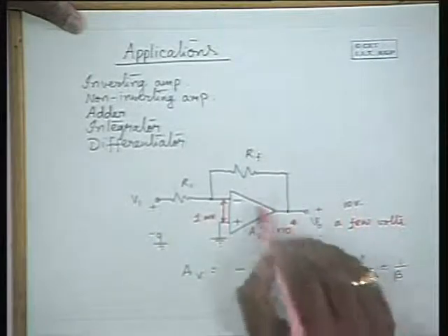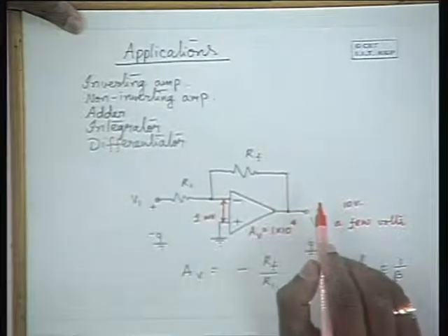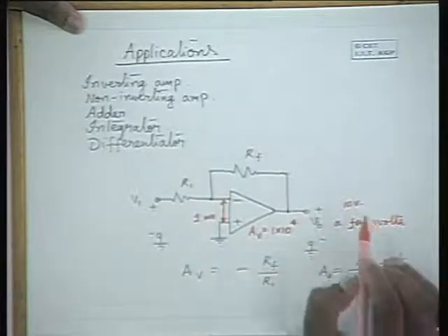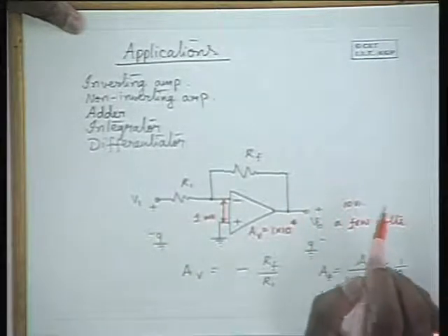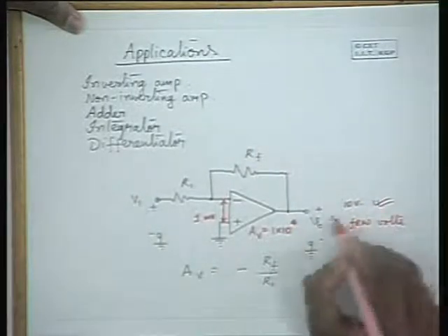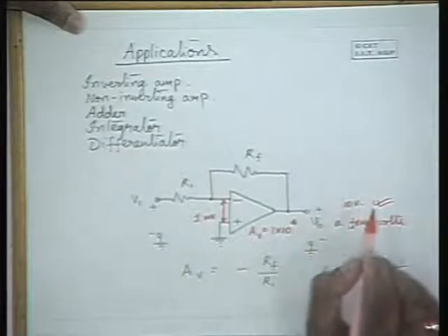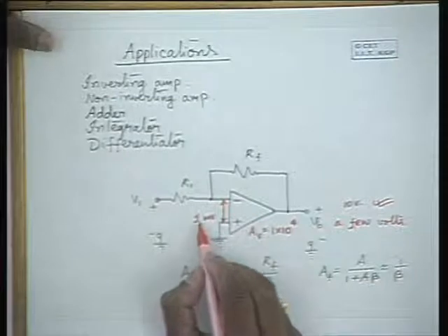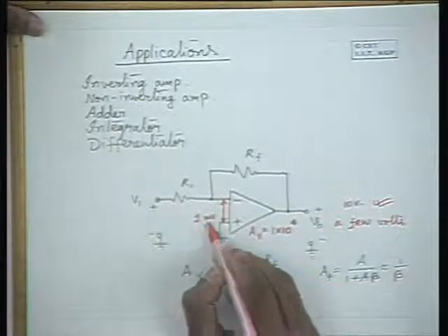And if the amplifier doesn't permit the output to rise to 1000 volts, it gets clipped, and you get a distorted output. But when the output is undistorted and of the order of a few volts, it means that somehow the input voltage is of the order of a millivolt.